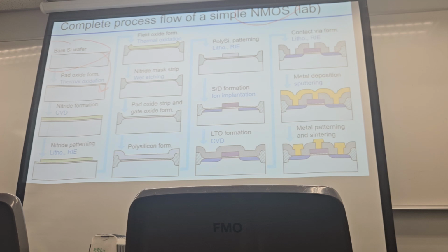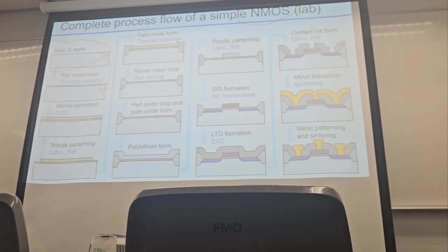So the pad oxide is formed, this is for the MOS, right? And there you have the silicon nitride. This silicon nitride can help you to remove the silicon dioxide in the region for the Schottky diode. Okay, so then from here we can create a region, open the region and remove the silicon dioxide. Yes, we need to create a region to remove the silicon dioxide.